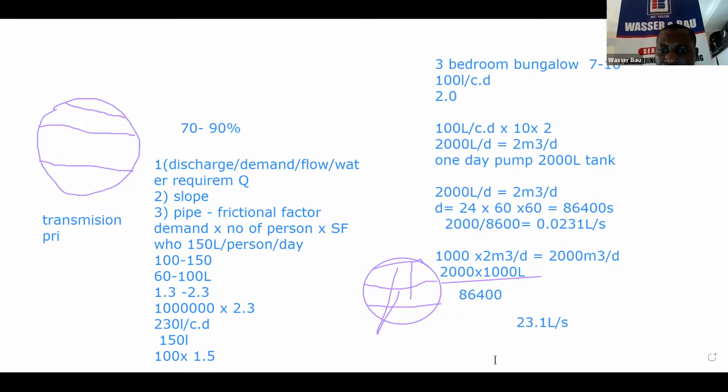Industrial nodes with 2942 now means they've computed the population and the water demand. So our job will now be, if you reduce it to the barest minimum, we now go to our charts. Can we open those charts? So let me open the charts. I'm using a PVC pipe, so I can open the chart with the 0.1 frictional factor.